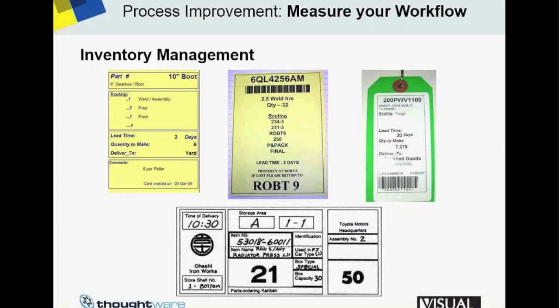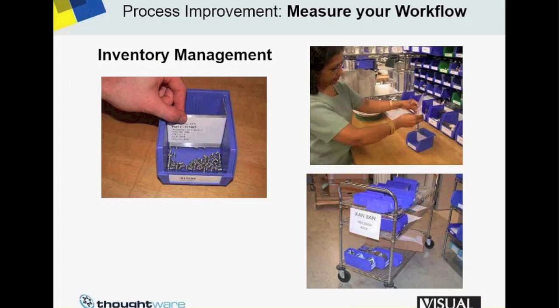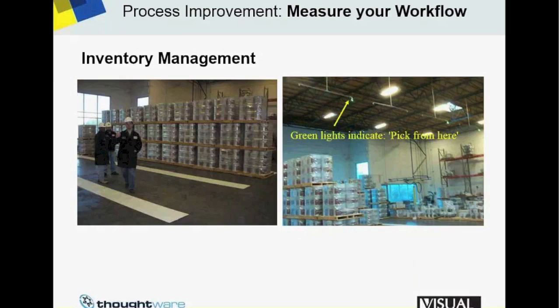Cards can be used to pull from upstream, from the cell, or from the vendor, with all the required information of standard work to operate. It can be a two-bin system used to pull from central stores or for direct vendor restocking, often to present right-sized parts supply to our assembly cell. It can be manifested in flow lanes, visual management of high-moving stock.